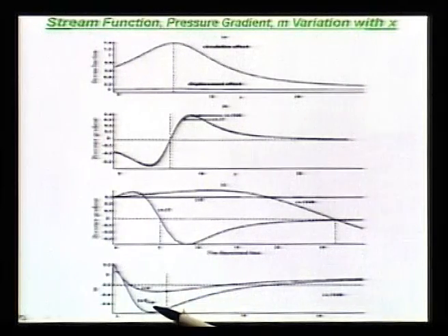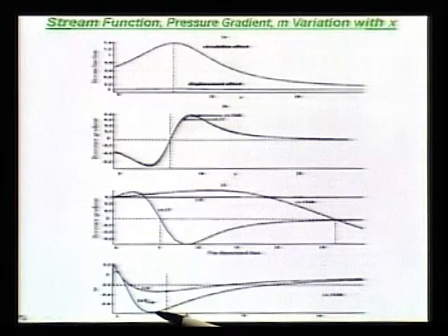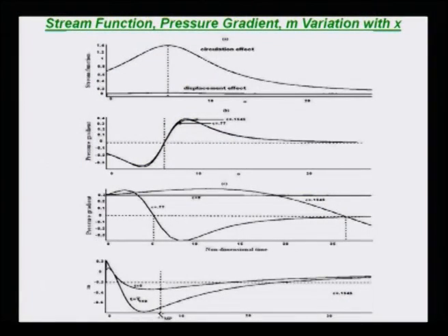You can see this is the case where you get the maximum adverse pressure gradient at this location. This is roughly around t equal to 23, maximum adverse pressure gradient is here, but at this location shown by this dotted line you see that first primary bubble, where the unsteady separation starts from that point.